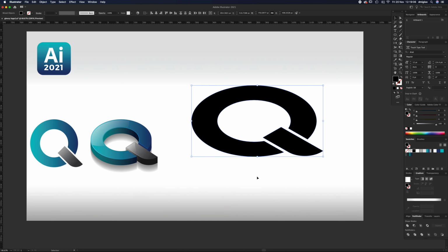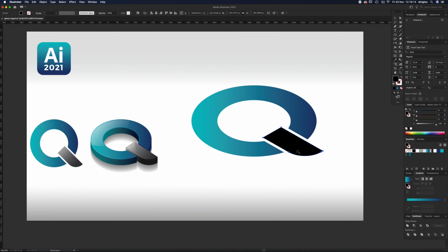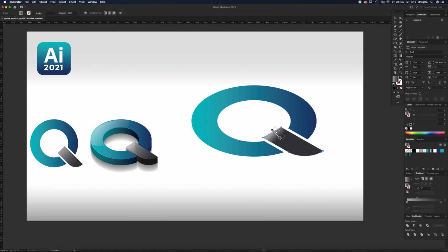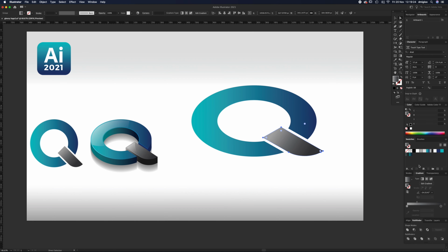Okay, and we can go ahead and add a gradient color if we want to, the ones we've already got pre-programmed in, and select your grey over here. And your gradient on this one wants to run from this edge down to there. In fact, we can go ahead and make this gradient, select this one here, which is 90%. We can make that 95%. So we've got those are the values on the left, and these are the values on the right.